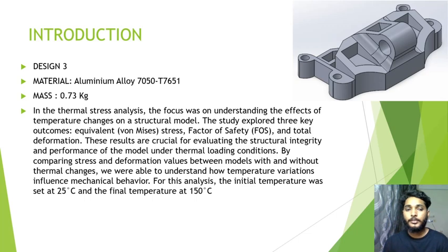By comparing the stress and deformation values between models with and without thermal change, we are able to understand how temperature variation influences mechanical behavior. For this analysis, an initial temperature was set at 25 Celsius and the final temperature at 150 Celsius. Both temperatures were taken from references on the internet.